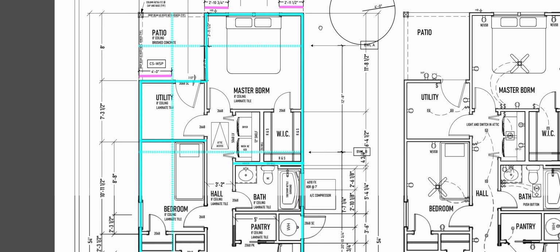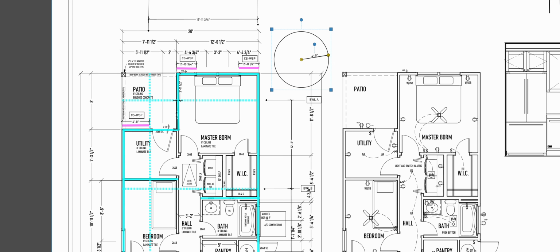So the max I can go for steepness on a lead and brace, and I want as much length as I can squeeze out of these, is I can go at a 45-degree angle, which means if my wall is 8 feet tall, then I can go 8 feet, even though the wall's technically a few inches over that. It's like an inch and 1/8 or something. I'm just going to round to 8 feet. All right. So I'm going to take my circle. That's my 4-foot circle. I'm going to leave him there. Actually, I'm not. 4-foot circle's diameter is 8 feet. Oops.